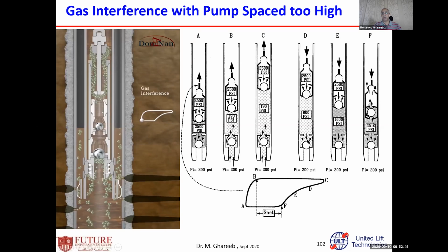But below the pump and the valves here, what happened? This is a fluid with gas. The valve here would change the direction of the fluid, and this becomes a closed cylinder, a closed loop. Then the traveling valve starts to compress the fluid with the plunger, but it compresses the fluid just gradually, because the motion is gradual.